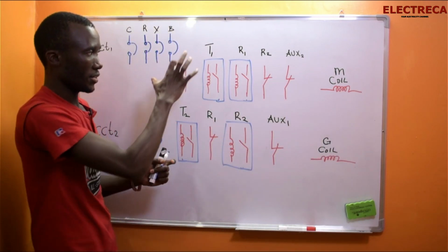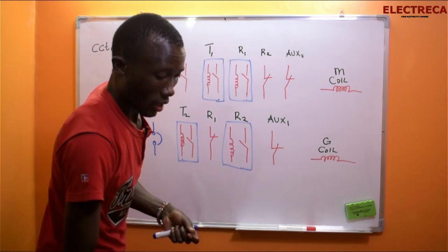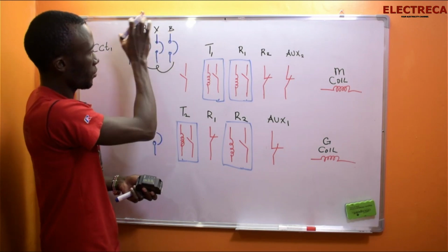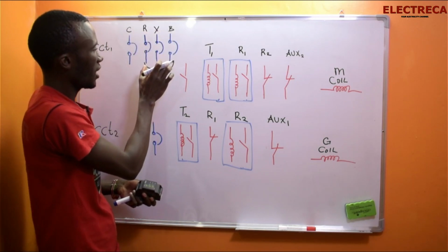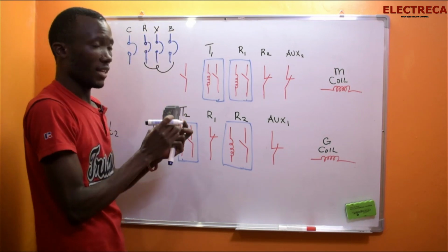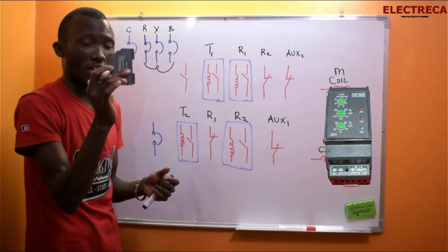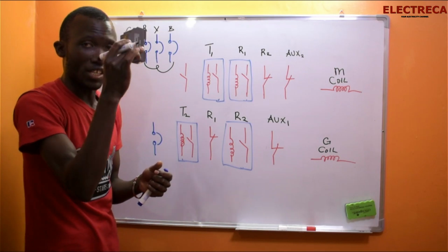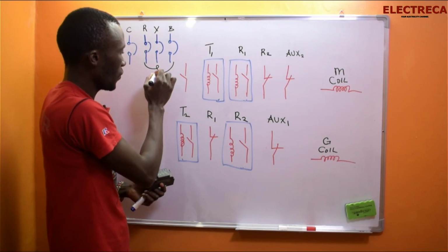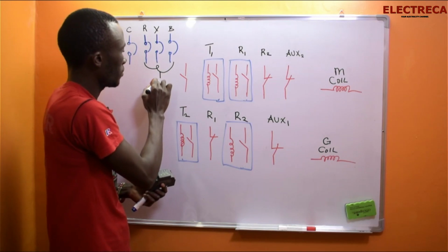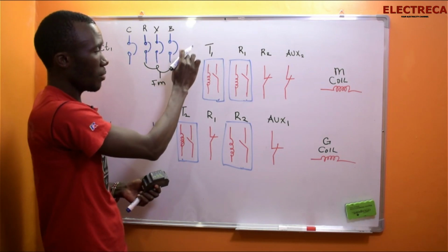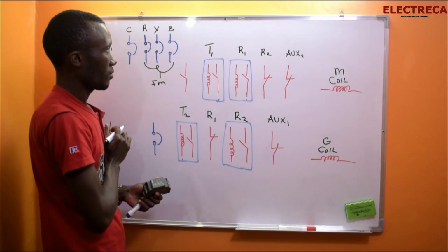So let's start from the upper one. The first breakers here are circuit breakers. The first three breakers here are control breakers, and they supply this because we need to put three-phase here to be monitored by this gadget. So all of these are entering our phase failure relay, our phase monitor. Right here, this is the normally open contact of your phase monitor.